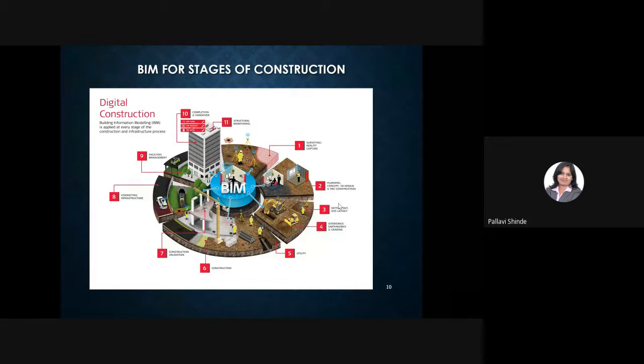The LOD of the project, LOD is level of development. So what will be the LOD of the project at which the project is awarded? It can be LOD 100, it can be LOD 200, it can be LOD 300. I'm not going to explain LOD in this particular presentation, but I'm just going to give you an overview. So we have multiple things which need to be set contractually between all the consultants, that what exactly is expected out of each and every consultant before creating this particular BIM model. And that document is called the BIM execution plan.